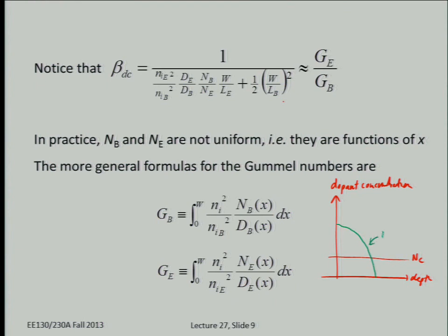Okay, so this might be the base doping profile as a function of depth. So it's not uniform. And then finally, we would introduce maybe even more heavily doped emitter that's rather shallow. And it's also a function of depth, certainly not a uniform dopant concentration within the emitter region. So let's sketch this. Where the dopant concentrations are equal, those are the metallurgical junctions. So this is where the collector is, and then you have the base region here, and then we have the shallow emitter region there. But you see the key here is that the dopant concentration in reality is not going to be a nice box-shaped profile. It's going to be dependent on the depth.